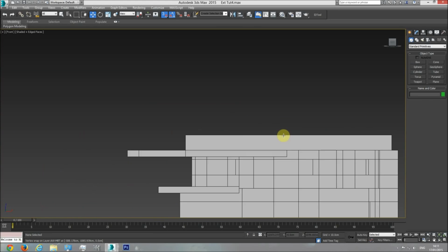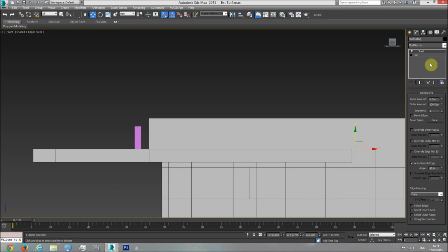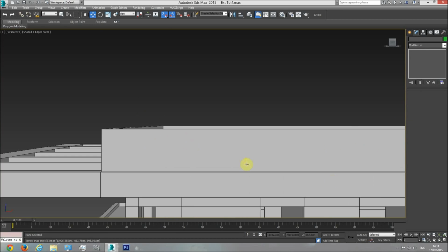89 centimeters. So let's go to the front viewport, try to create a box 89 centimeters high and place it down here. So as you can see, it's too high. I'm going to make it shorter. I'm going to give it a value of 89. That is correct. And let's delete this helper.